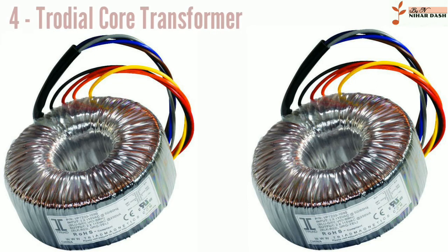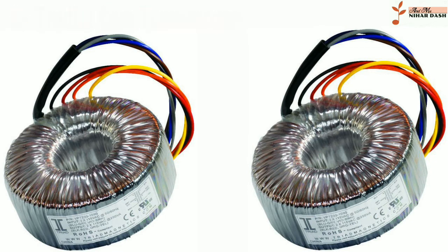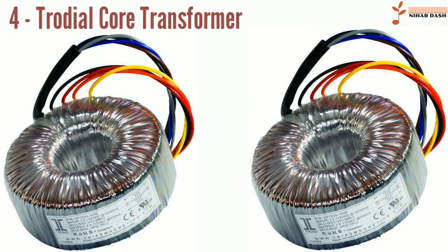A drawback of toroidal transformer construction is the higher labor cost of winding. This is because it is necessary to pass the entire length of a coil winding through the core aperture each time a single turn is added to the coil. As a consequence, toroidal transformers rated more than a few kVA are uncommon. Relatively few toroids are offered with power ratings above 10 kVA, and practically none above 25 kVA.